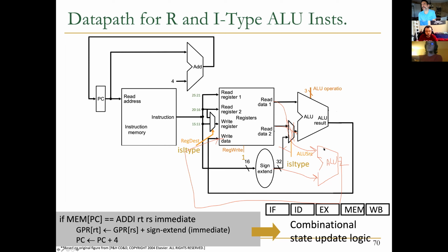Do you see any problem here? You have two ALU signals going to the same place. That is the biggest problem that I see. Yeah, you still have to figure out how to choose between the two output ALU signals. Imagine that we will send the right control signal, so we find a way of wiring the right bits into here. For example, depending on whether this is R type or I type, you send the right signal to allow either of these ALUs to be used, right?